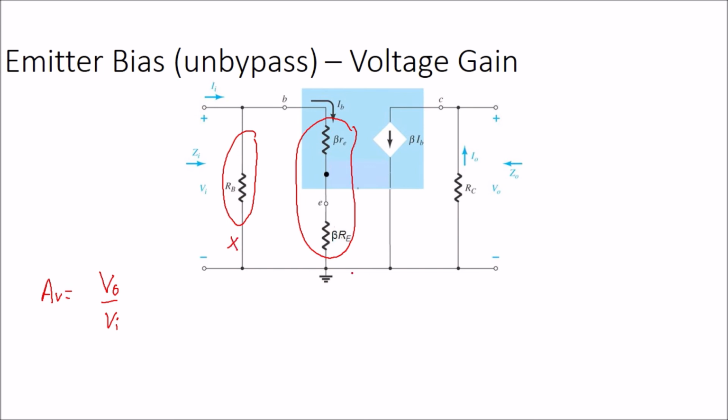So what we're going to do is use this voltage, where the value of current is given as IB, and we also have all the information regarding the resistor. So Vin is equal to IB times the total impedance that we represented in terms of ZB just now. So IB times beta RE plus RE.